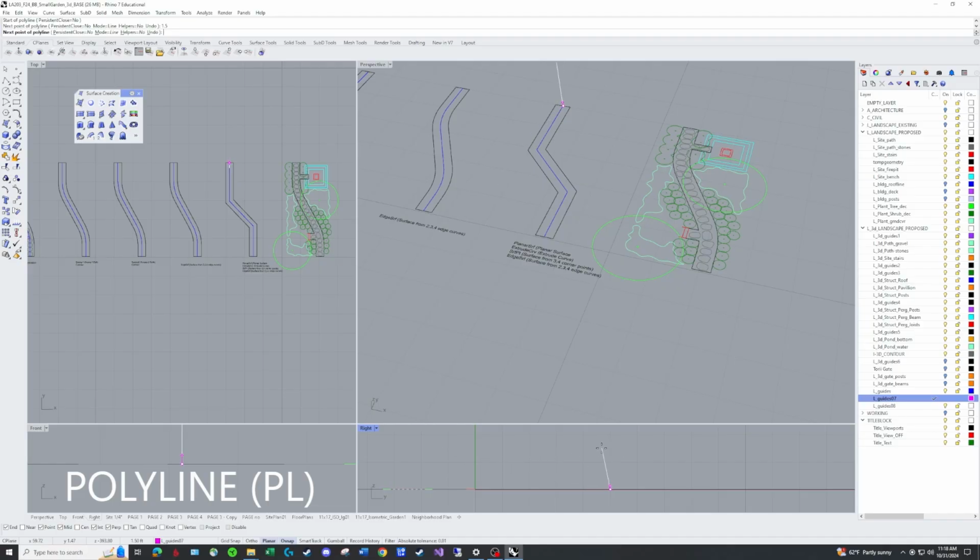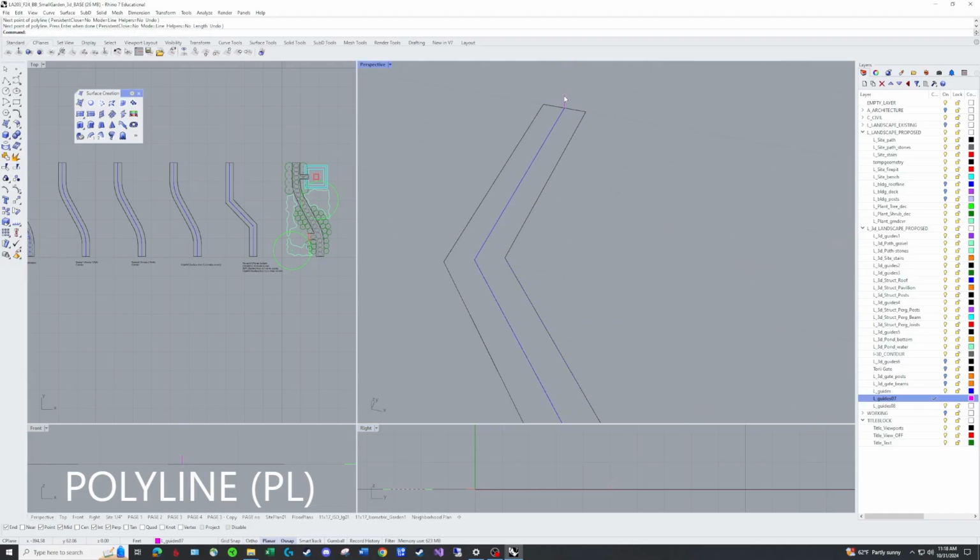viewport. And I'm going to temporarily engage ortho. So I'm going to hold shift down and notice that now when I move it, it either goes 90 degrees flat or straight up and down. Otherwise, it's doing all of this stuff. So hold ortho and then left click, and then you can space bar enter, and you now have a line